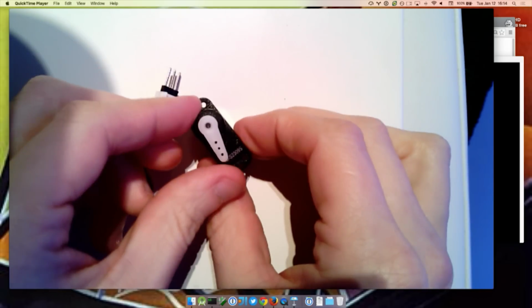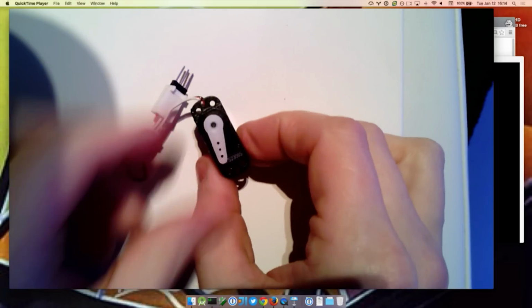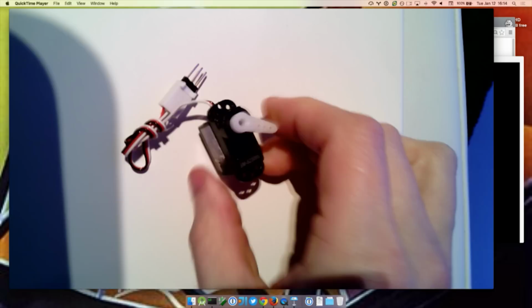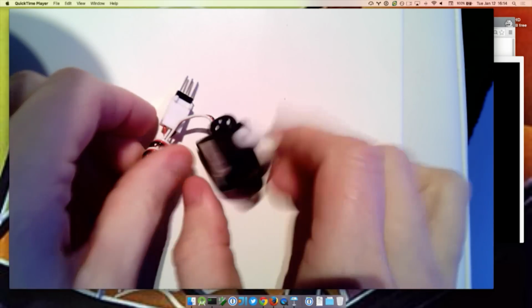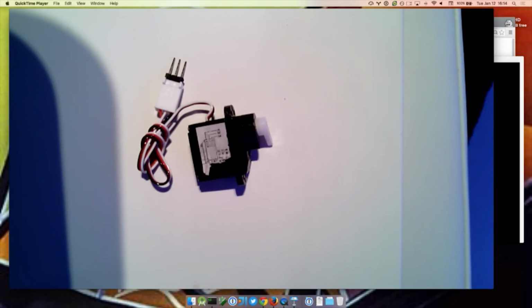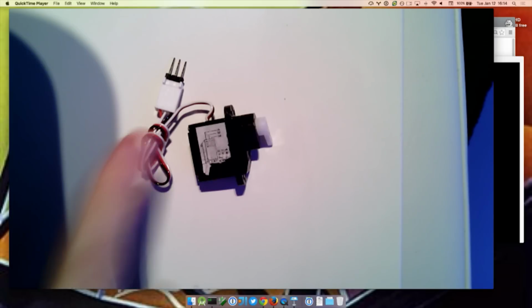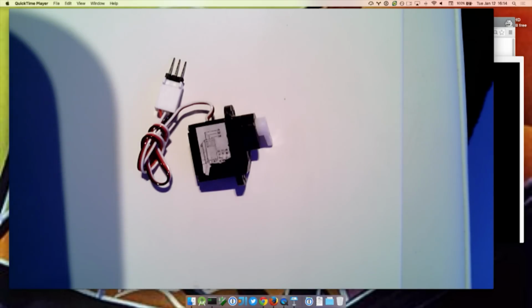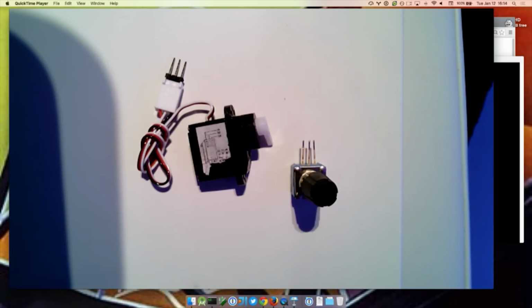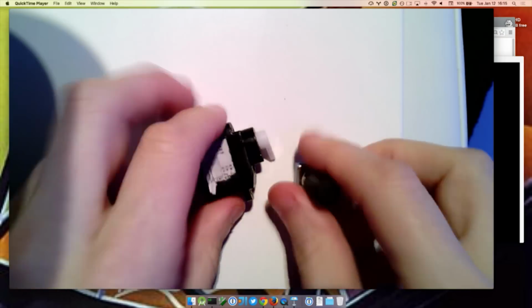And a servo motor is kind of like the opposite of a potentiometer. It has a little arm that moves. Generally, you don't want to play with them while they're off like this, but I want to show you. It's also a 3-pin device, and if you give it a ground on one side, voltage on the other, and then a PWM input in the middle, it'll go to the ratio of that. So you can actually do an analog input on a potentiometer, turn it, and then make the servo motor move by converting that to PWM and outputting it.